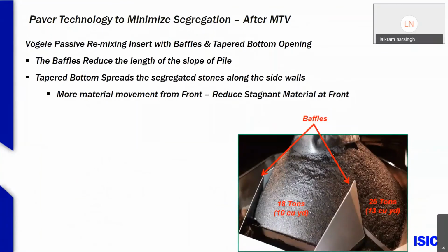Hopper insert is usually one of the culprits for segregation under the bearing hanger. Todd had a nice slide there where he showed with a thermal profile segregation under the auger box, but right outside of that, under the bearing hanger, was also 2 continuous streaks. Those streaks come from any material that rolls to the sidewall, rolls on the side of the slope of the pile in the insert, hits the sidewall, and follows the sidewall to the edge of the conveyor chain, which is almost in line with the bearing hanger.